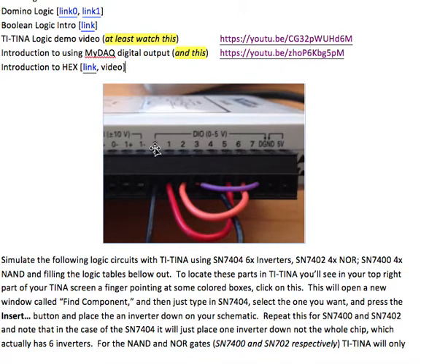I'm treating pins 0 through 3 as my digital output pins, and 4 through 7 as my digital input pins, so I can read that. As you can see, I hooked up 0 to 4 with this black wire, I hooked 1 up to 5 with this red wire, I hooked up 2 to 6 with this orange wire, and 3 to 7 with this purple wire.